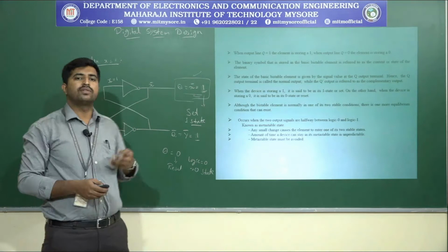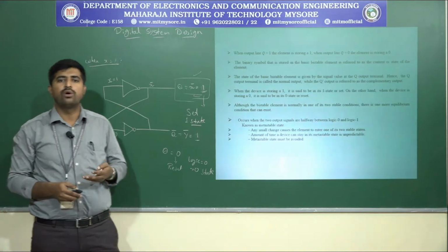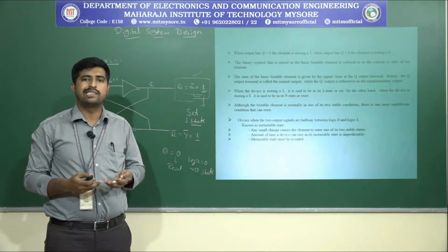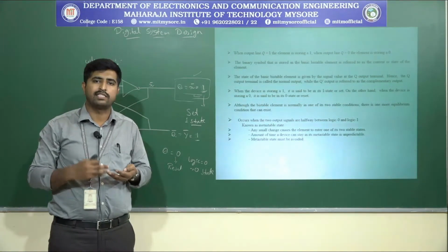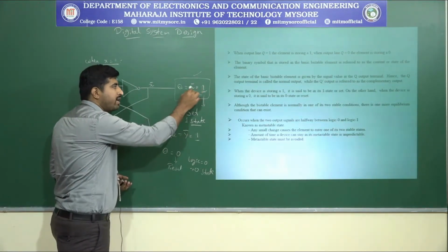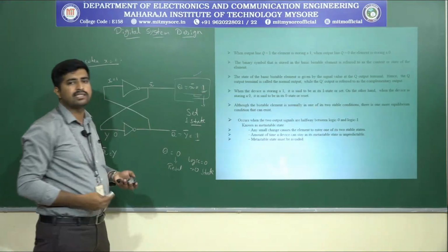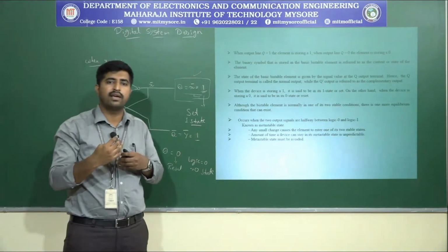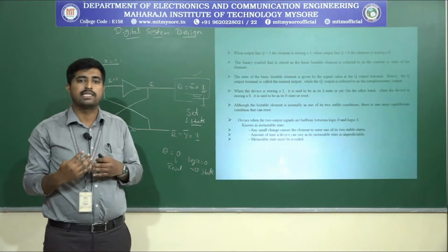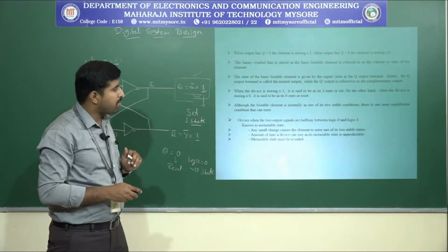So the basic bistable element has two stable conditions. There are no other states. But when the logical symbol is not exactly identifiable as logic 0 or logic 1, for example due to some noise in the circuit, that is called a metastable state, where we are not able to identify whether it is a logic 0 or a logic 1. So this other state may occur.